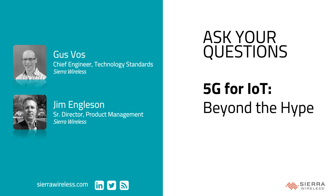Wow, that's a really good question. It's kind of a little loaded, I think. Maybe I want to make sure that I'm answering the right question. So remember that, of course, the LPWA use case, I mentioned this a few times in my presentation, is only supported by NB-IoT and LTE-M, right? LTE and NR doesn't support this LPWA use case. And also, as I presented, Release 16, the second release of NR, also doesn't support this LPWA use case. So we have no support at all for this use case in NR.